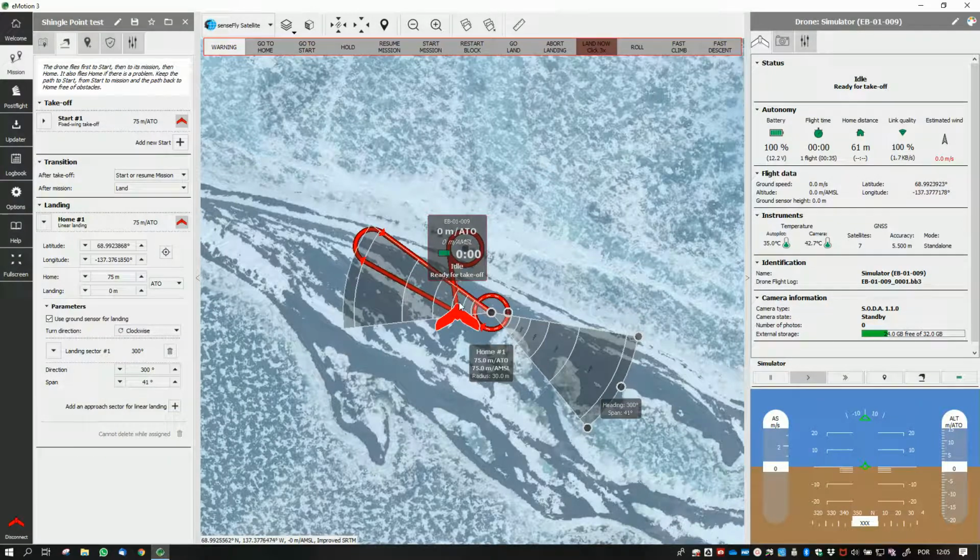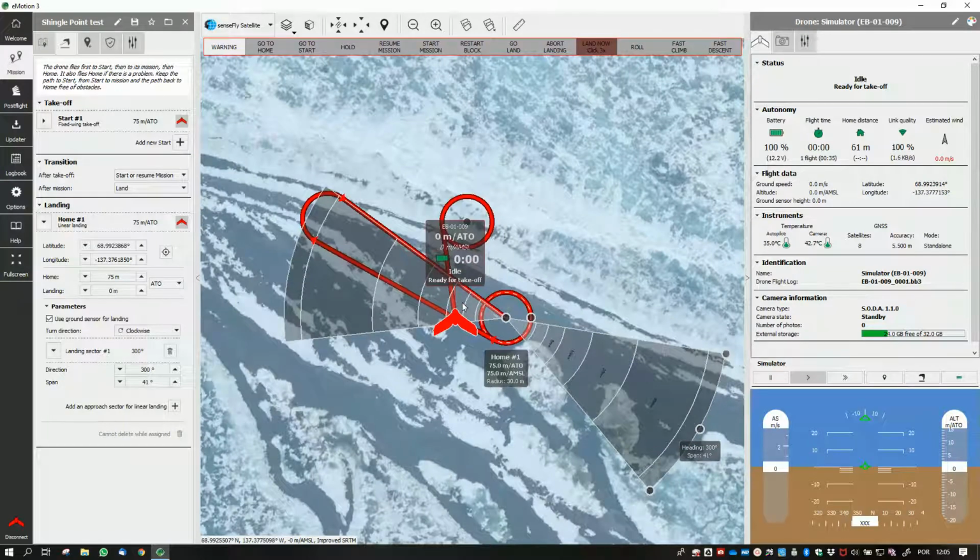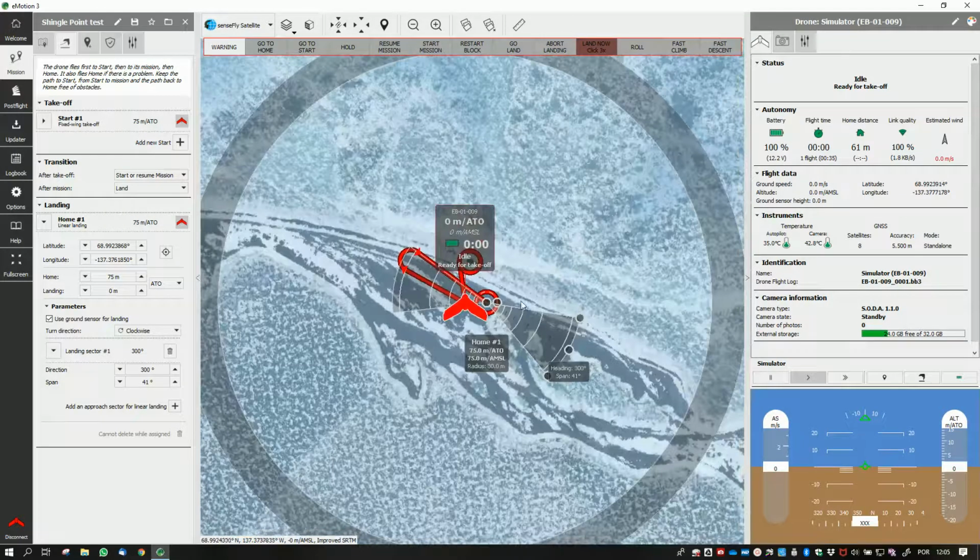Remember that the drone, when landing, can disconnect itself and stall. Normally it does it from 2 meters above the ground, but if it is not measuring the distance accurately, it will stall from 10 meters above the ground, which means that if it's windy, it will be thrown to a great distance. You want to avoid it falling in the water. So be really careful when planning for the landing. Ideally, the landing site should be the furthest away from the ocean.